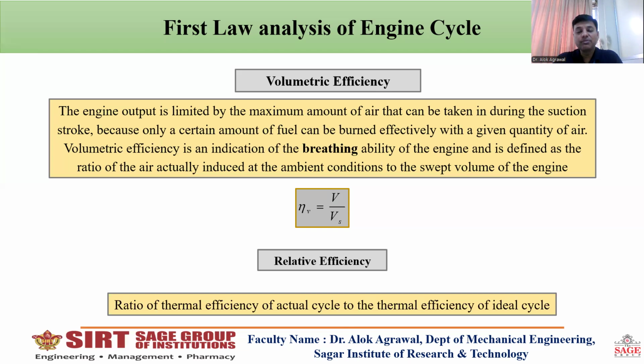This is the maximum thermal efficiency when the engine works on the ideal cycle. But in actual, it is not the case. The actual engine will not follow exactly the Otto cycle. Why? Because the Otto cycle is an ideal cycle. It is designed for the SI engine to give maximum efficiency, which is 1 minus 1 upon r, the compression ratio, to the power gamma minus 1.